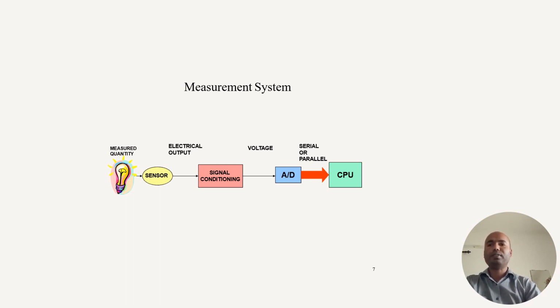Then after that we have to select a suitable sensor. Sensors get power from the battery at different levels, either 5 volt or 10 volt or 12 volt, sometimes more than that also. Some sensors work without external power; while actuating, they produce power, like knock sensors. Different kinds of sensors are there, so you have to select the proper sensors.